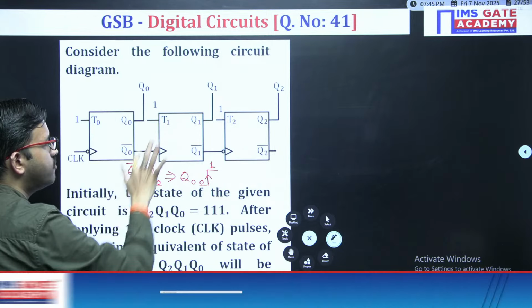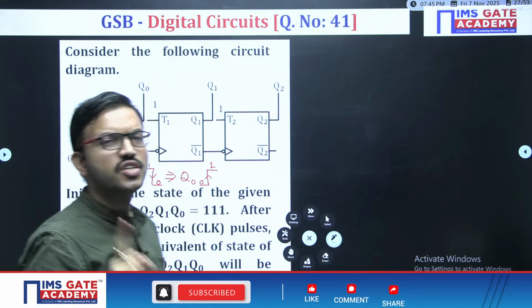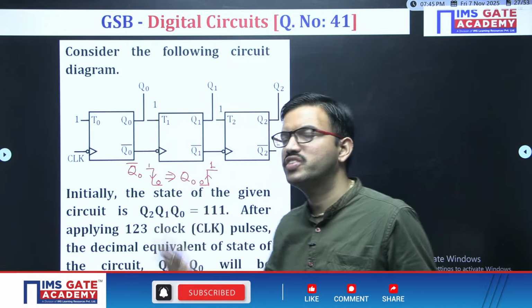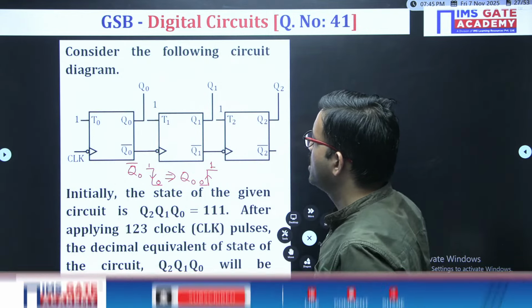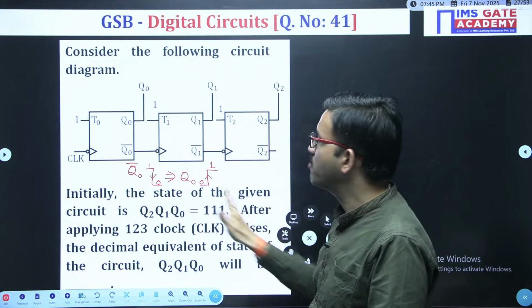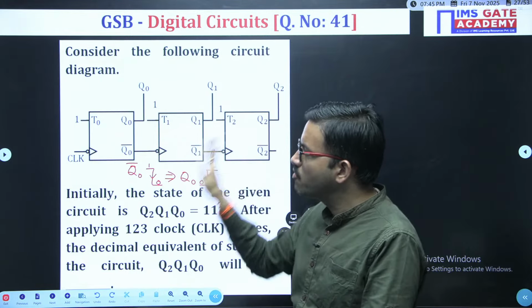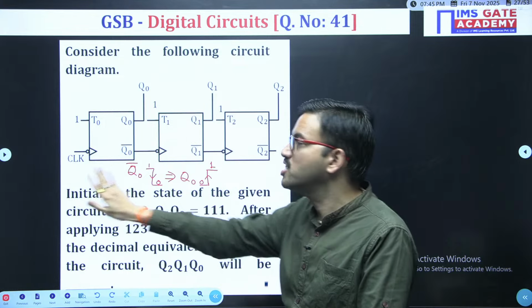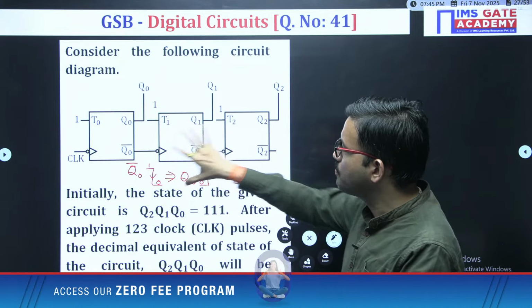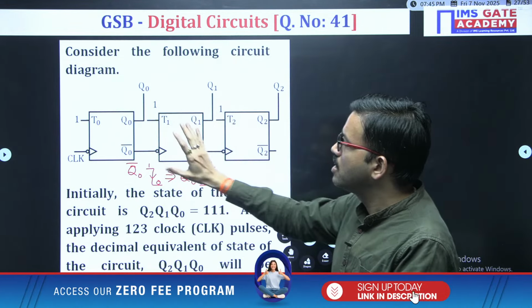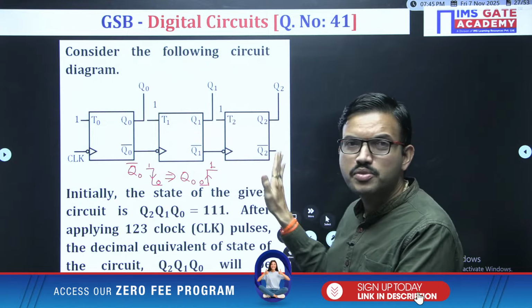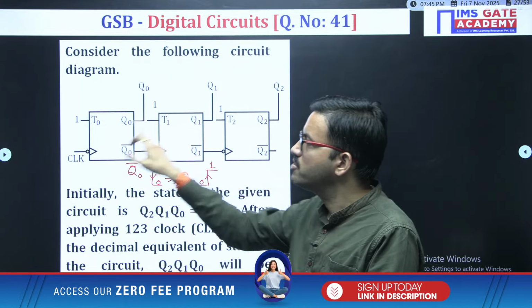See, regarding the first stage flip-flop, it is completely optional whether you consider positive edge or negative edge. But for the overall circuit, when you have n stages and all are negative edge, for uniformity we use negative edge here also. Similarly, if the remaining flip-flops other than the first stage use positive edge, for uniformity we use positive edge here also.